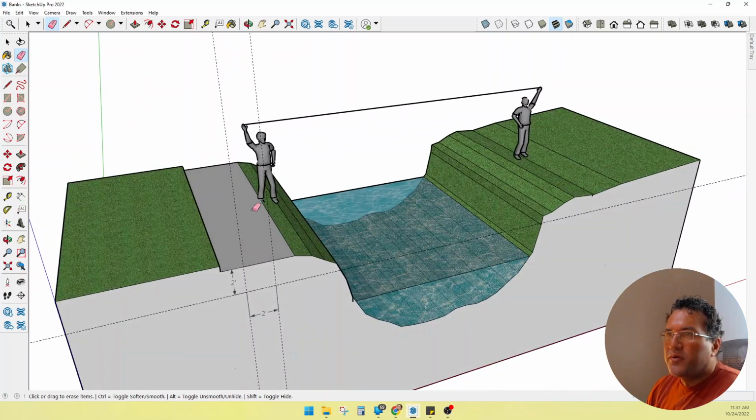The other direction, going across this way, that's really going to depend on the width of your bridge. We typically plan on, if your bridge is going to be 8 foot wide, building this 1 foot wider on each side. So an 8 foot wide bridge, you want about a 10 foot wide abutment. Okay, so if you're using an 8 foot bridge, your trough or your area here would be 10 foot by 2 foot by 2 foot. Okay, pretty simple. If your bridge was 10 feet, you add 2 feet to that, 1 foot on each side, that'd be 12 foot by 2 foot by 2 foot. Okay, pretty simple. All right, so that's gravel.